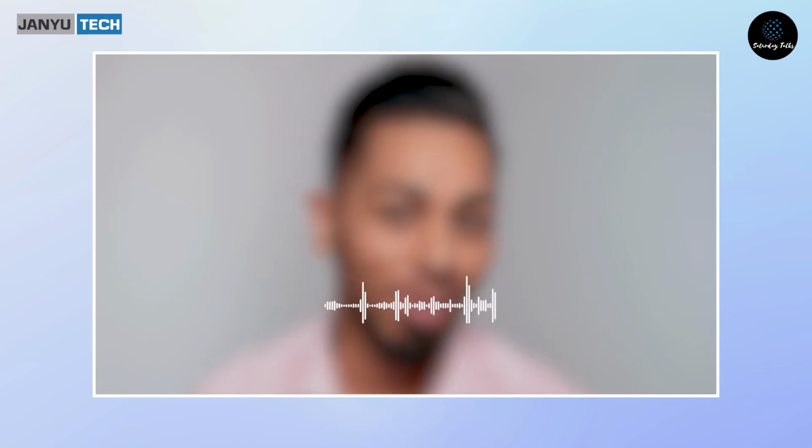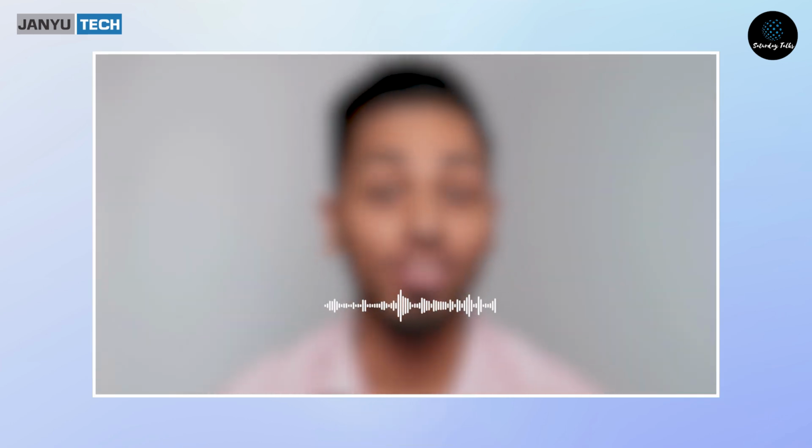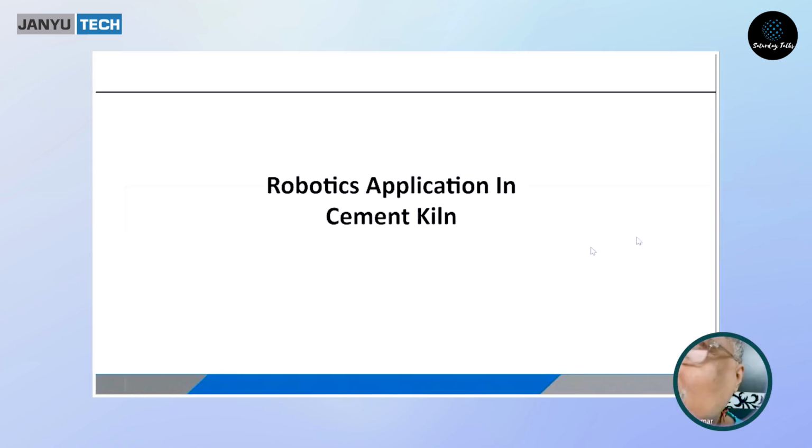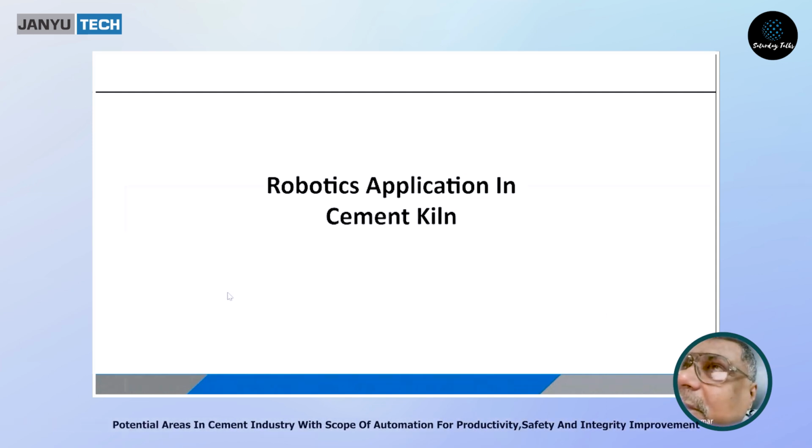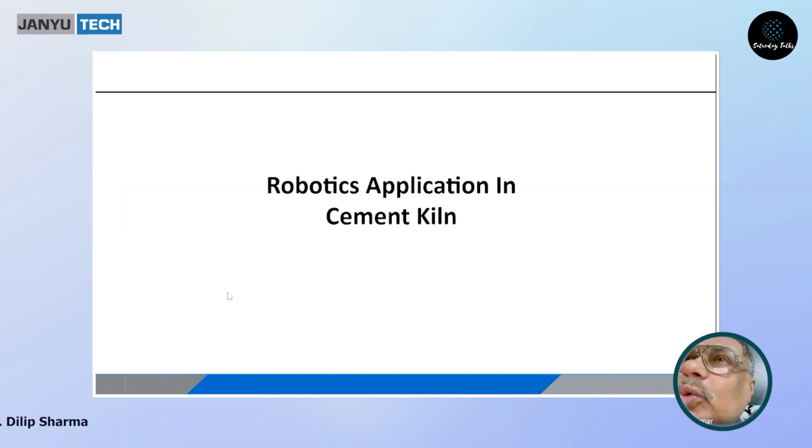Is it water dissolvable, for washing or something like a forced wash? No, there are 2-3 things. One is, I said, the moisture in the raw material, like slag. Slag has 12 to 15% moisture. Apart from that, in the mill itself, we are required to spray water in order to have a proper bed of clinker on the grinding table. Because if the bed is not formed, then the roller would skid and the mill would trip because of vibration.